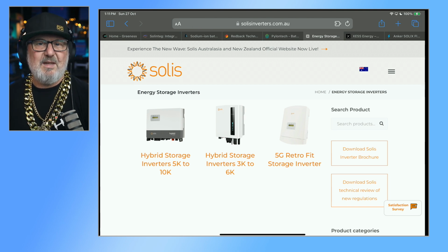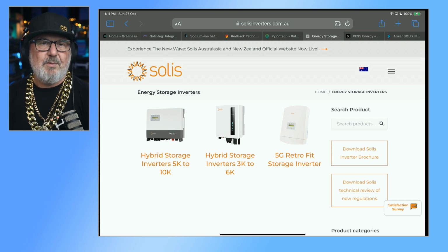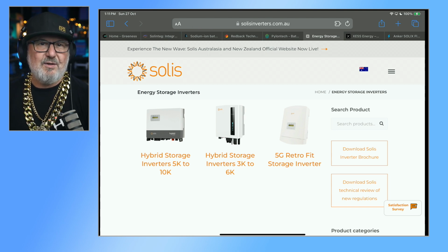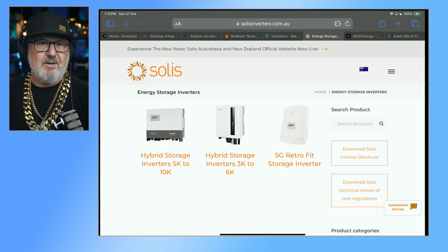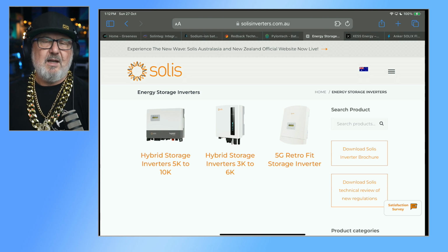What's that for? Well, it means that if you're a grid-connected system with a battery storage and some PV connected, you've essentially got three forms of energy. You've got solar during the day, you've got battery whenever you need it, and you've got the grid when it's available. But during extended outages, when the grid's not available and it's nighttime, depending on the capacity of your battery system, you might just run out of battery. Now, if you want the ultimate in reliability, having a backup generator is a great idea, and that can be integrated directly into the generator port on the 8 kilowatt hybrid plus. So it's got a third AC port.